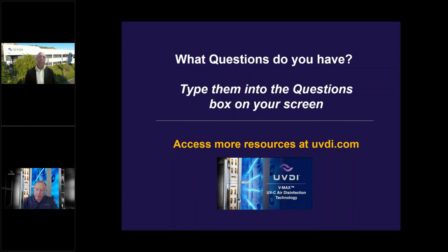Great, thanks. You talked a lot about the portable air cleaners. What's CADR? I've seen that, and that's come up as a question. What does that mean, and how does that apply to what you've been talking about? Yeah, CADR is clean air delivery rate. It's really not an ASHRAE standard. It's an AHAM standard, more for residential air cleaning. 185.3 is really the standard you need for buildings. But the CADR rating is really what is used to measure the general effectiveness of air purifiers.